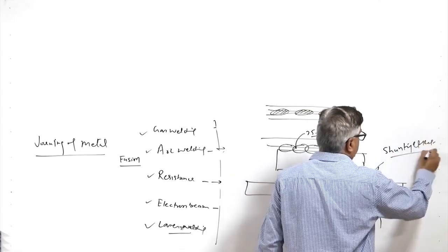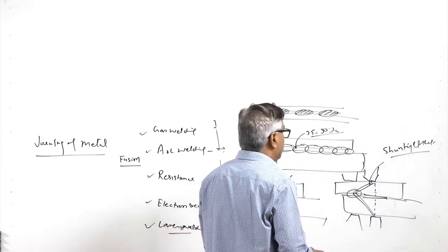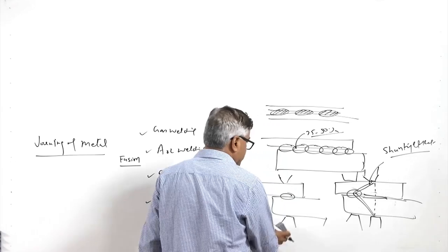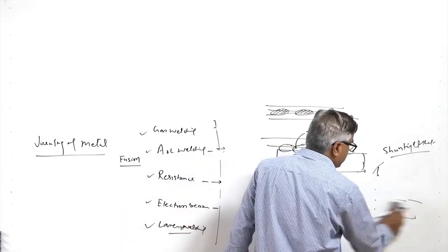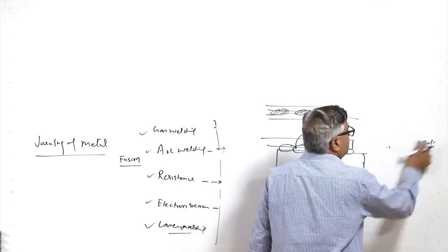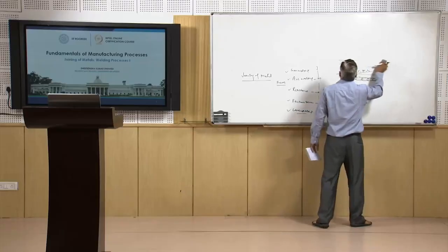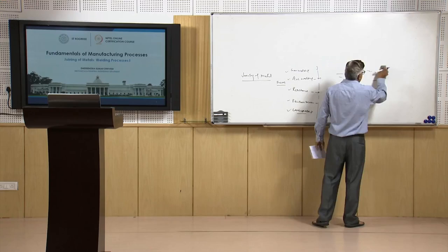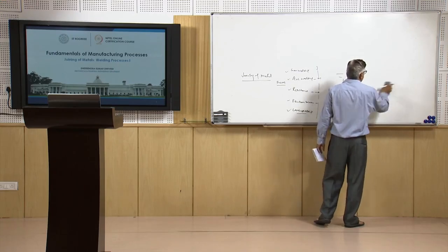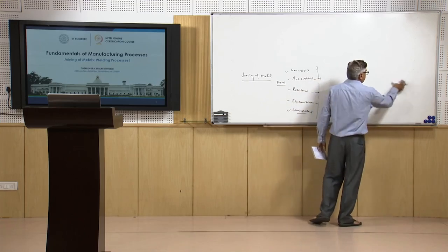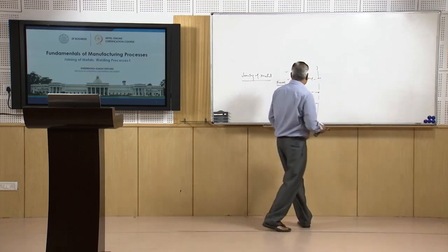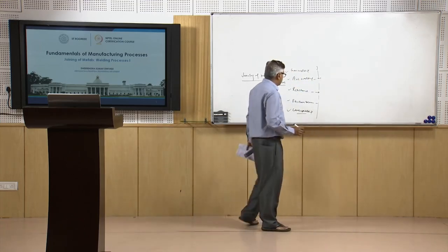because of which much higher current is required when a number of spots are to be made. That is why, when a seam weld is made, we see that the welding current requirement increases too high because of the increased shunting effect due to the continuous overlapping spot development during welding.